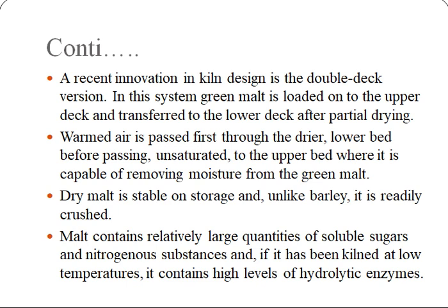A recent innovation in kiln design is the double deck version. In this system, green malt is loaded on the upper deck and transferred to the lower deck after partial drying. So the green malt moves from top to the bottom, and the drying medium, that is warmed air, moves from the lower to the upper portion.